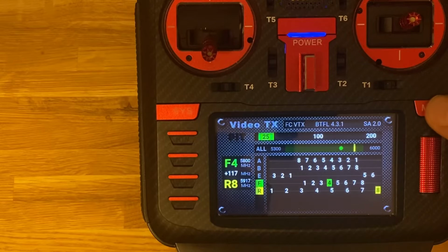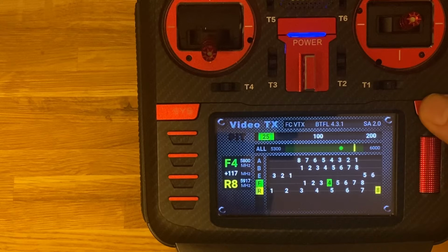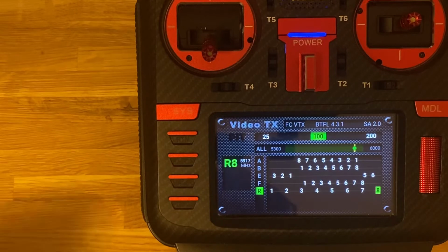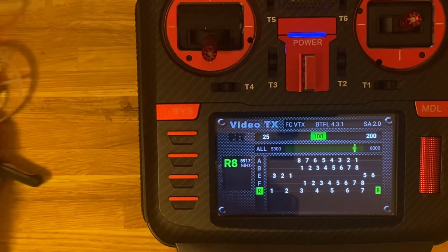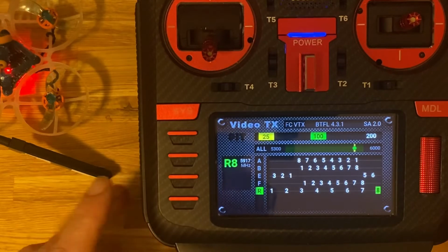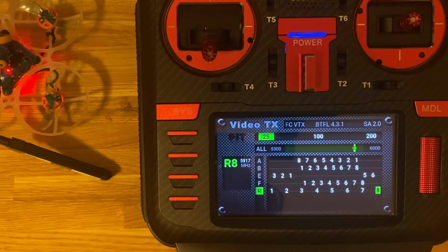Okay, another one is power level, because you can also change the power levels. And to change, you short press model, so it will go to the next value. Of course, if there is no yellow marker, it means the selected one is current, so no change. So let's change, for example, to R8 and 100 milliwatts of VTX power. The new channel will start to blink, it's fast. So now it's on R8. You have to believe me, I don't have a preview. So to go back to 25, I will set it to 25. I will not change the channels, so only power will be changed.